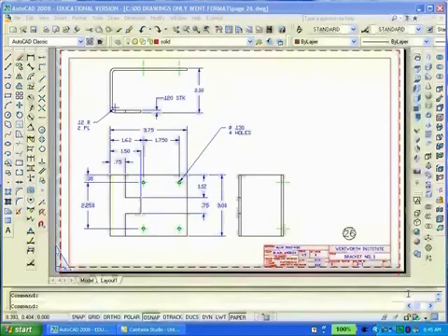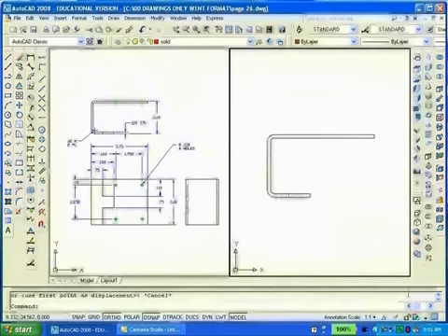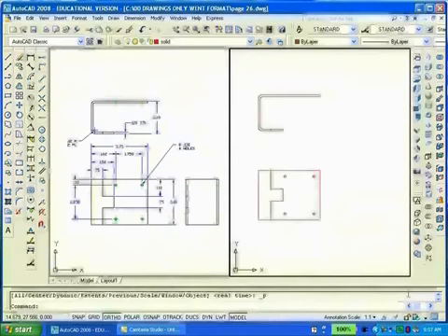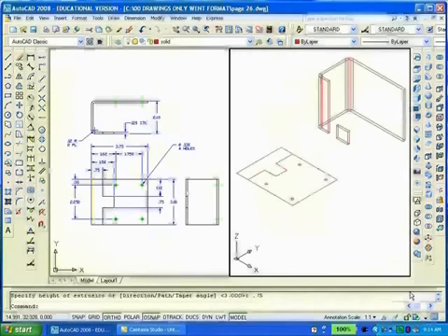This is an abstract of tutorial 26. In this drawing, I used a polyline to trace over the top view, subdividing it into two parts. Then I will move those profiles to the upper right, and of course make certain that both are closed polylines. I moved into the southeast isometric view and extruded the large profile to a height of 3 units and the smaller to a height of 7.75 units.